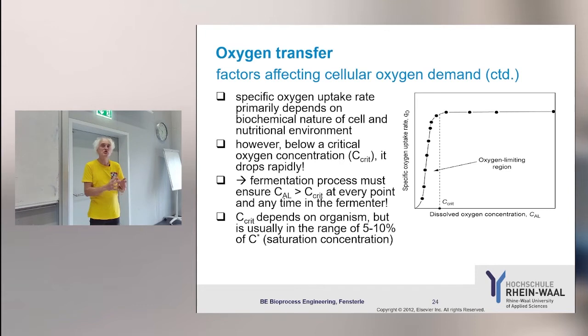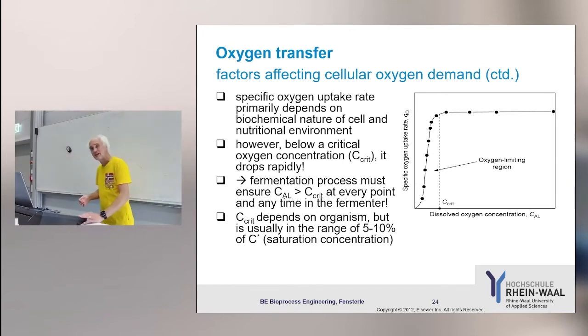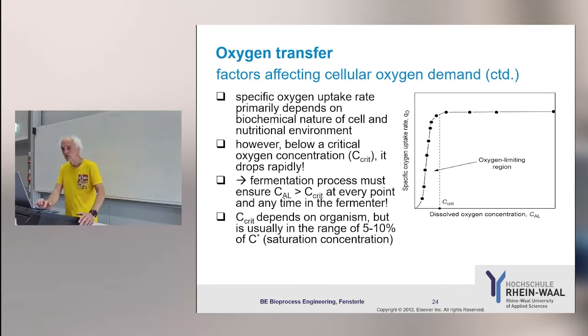So in other words, you don't want your oxygen concentration to go lower than this value, which makes us a bit sad, because the driving force of our transfer is such that the lower the concentration in the liquid phase, the higher the transfer rate. But we cannot go close to zero, because then the uptake of the cells will also go down.